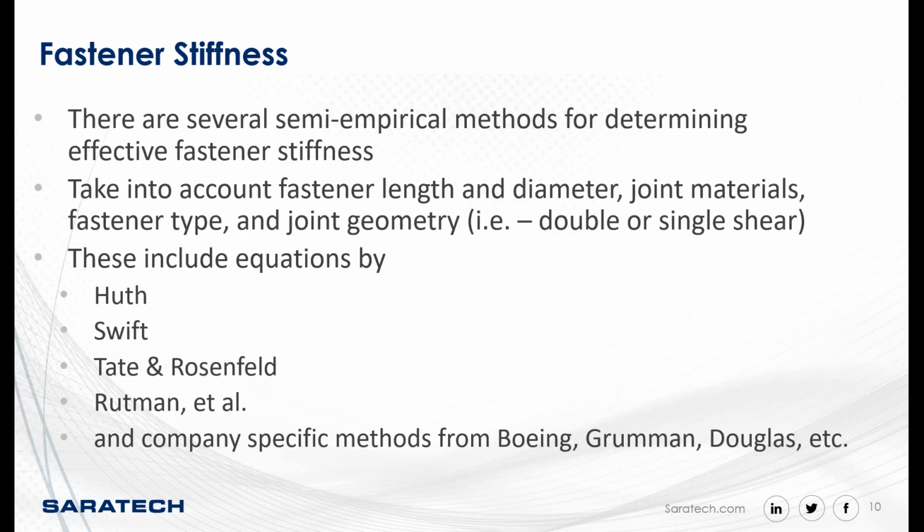So there are several semi-empirical methods for doing this that take into account factors like fastener length, diameter, materials, and so forth. They include equations you'll see used in industry: Huth, Swift, Tate and Rosenfeld.